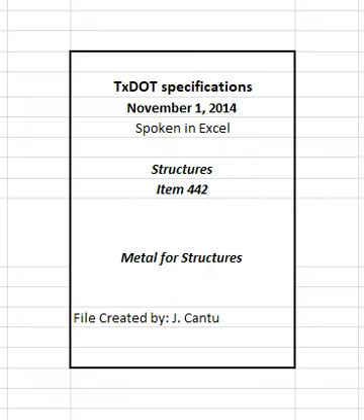2.1.1 Bridge structures. Provide the grade of ASTM A709 steel shown on the plans. Grade 50W, 50S, or HPS 50W may be substituted for grade 50 at no additional cost to the department. Use Zone 1 if no AASHTO temperature zone is shown on the plans. 2.1.2 Non-bridge structures.